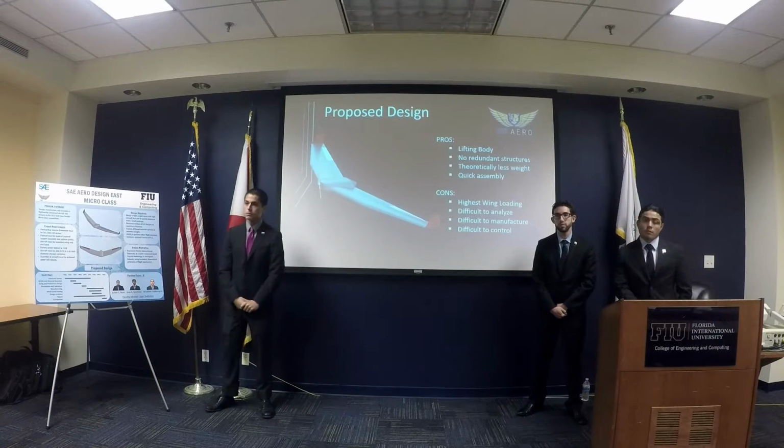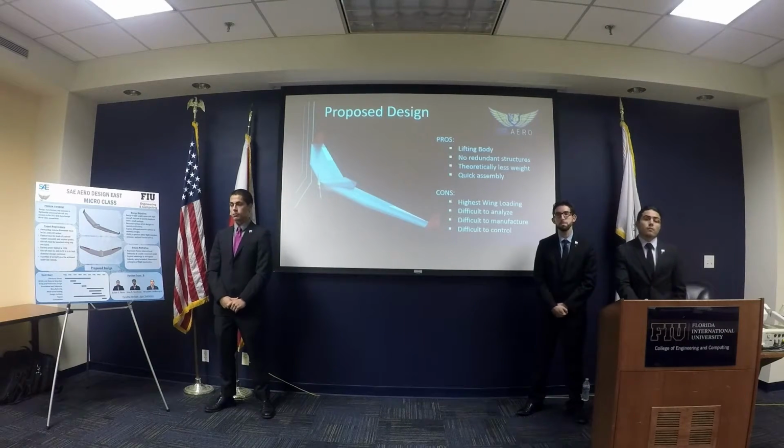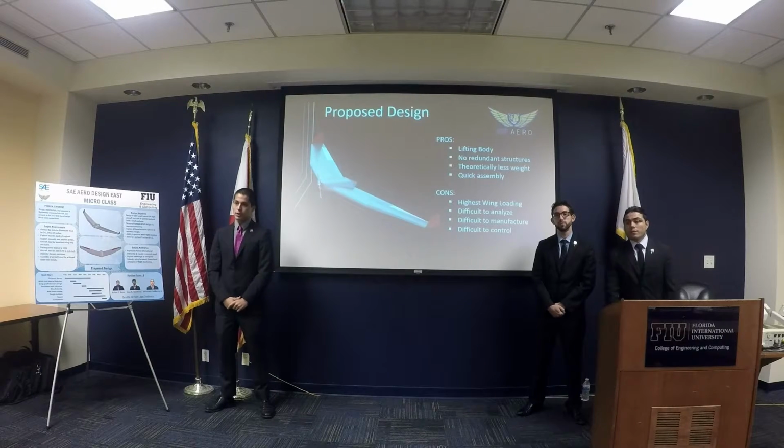So there are three ways you make a flying wing stable. You add dihedral, you sweep the wings, and you increase your drag at the wingtips. You have very low dihedral, you don't have a lot of sweep, and you're removing your drag using winglets.